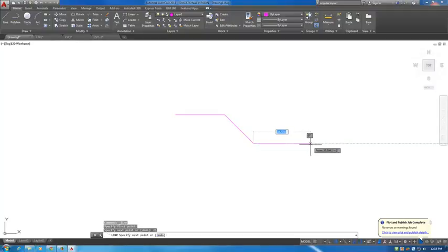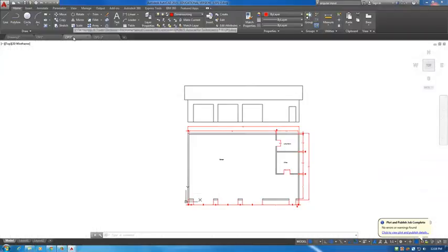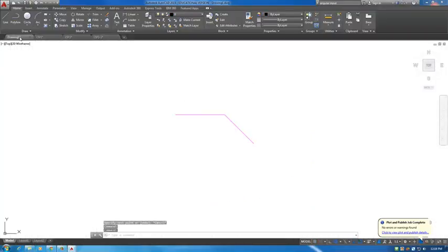Okay, so now let's just continue our line here. Going into this drawing, you see we go 50 units long. Oops, wrong one. So I'm going to start at this point here, again using polar, ortho, however you want to do it. Type in 50. Now remember, these are actual coordinates. They're not based off of 0, but they're based off the last point. So that makes them relative coordinates.